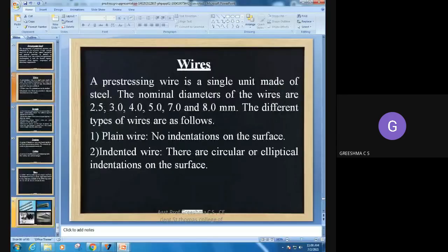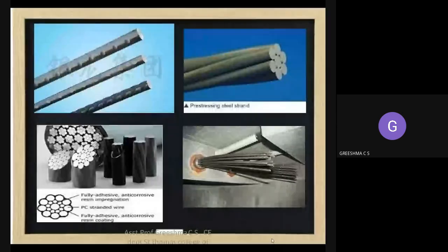Next, see this figure. For steel, in the first figure they have used plain bars. But nowadays we are using deformed bars. You can see these are deformed bars. Deformed bars give you more resistance. If you use deformed bars, the bond stress will be much higher, and slip will be less. This is how it is anchored. You can see in this figure the tendons are anchored over here.